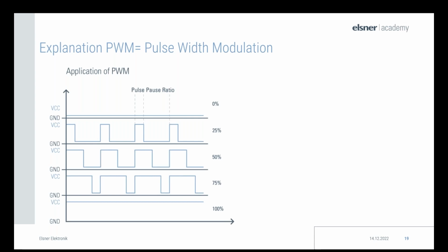All right, I just see there is a question coming up. One second, please. All right, the question was: any impact on the lifetime of the actuator with different pulse width? With our actuators, it does not have an influence because they have an electronic switching mechanism and not a relay mechanism. With other actuators, I can't tell. With ours, not.